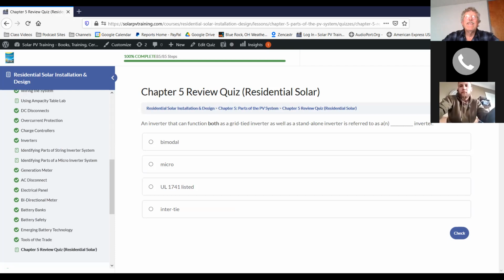Is that correct? Yeah, in effect, what you're going to be doing is reducing the irradiance. Of course, there's not as much power hitting that particular cell. And you remember there's a thing called bypass diodes within a particular panel. Otherwise, every cell in that panel would be affected by a leaf sitting on one cell. So usually there are 3 bypass diodes, so only a third of the panel is going to be affected. But every one in that string of cells is going to be affected.